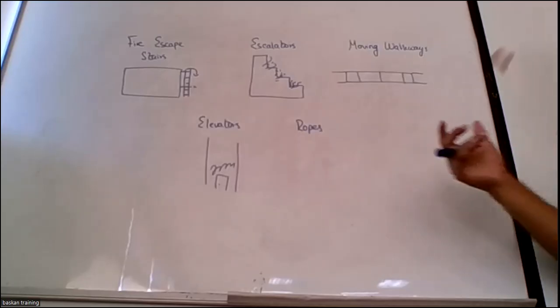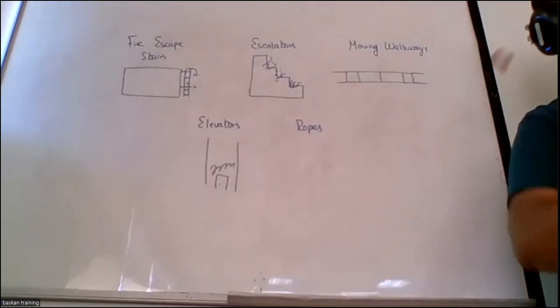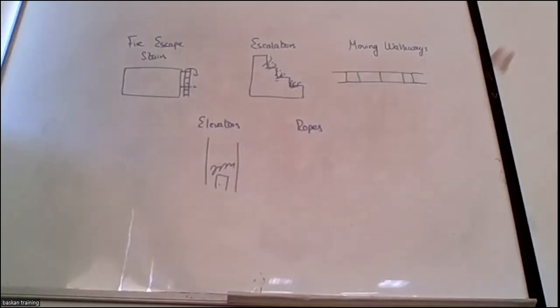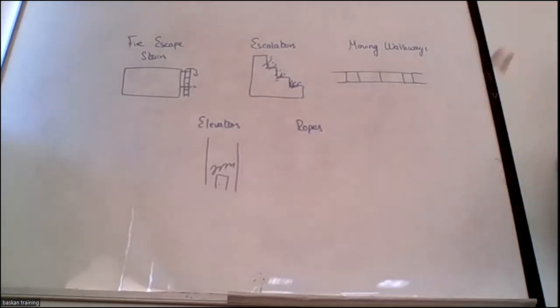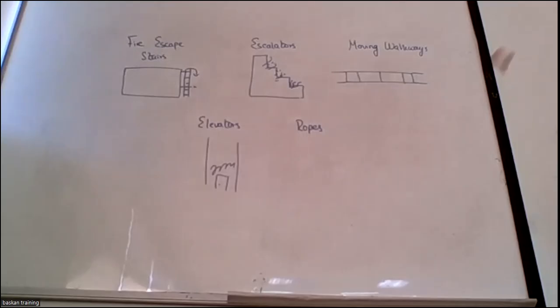So ropes are used in organizing fire rescue operations, and in fire rescue operations those ropes are different. But when you're talking about NFPA 101 and ropes and means of egress, when a means of egress comes, it means occupants' involvement. Like firefighters' lift is a firefighters' component. When it's asking me elevators as a means of egress, even if it's a firefighter elevator they are mentioning as a means of egress, for me as an occupant, it's not a means of egress. Ropes are not considered as means of egress. Windows are not considered as means of egress.